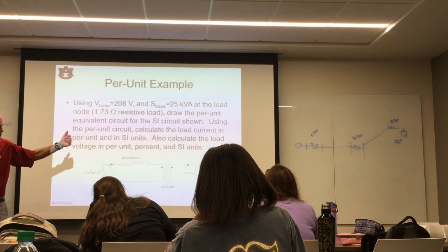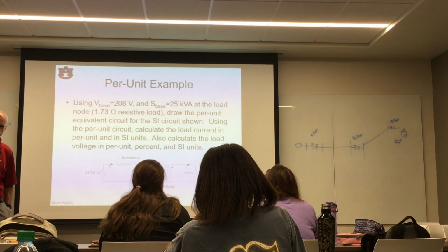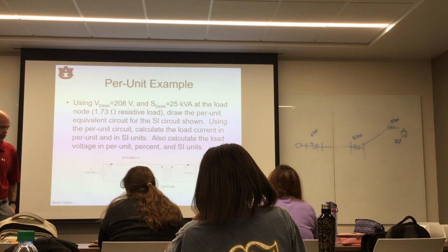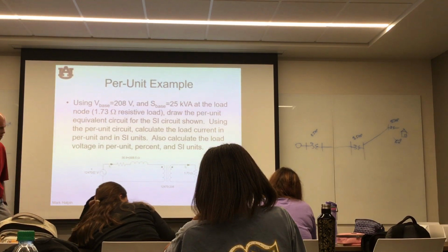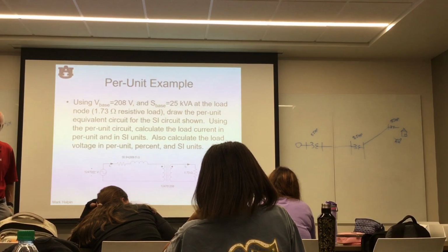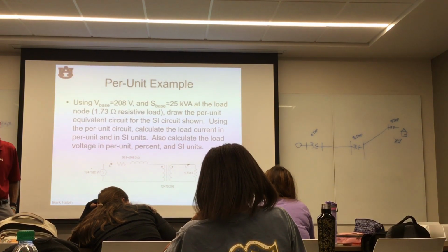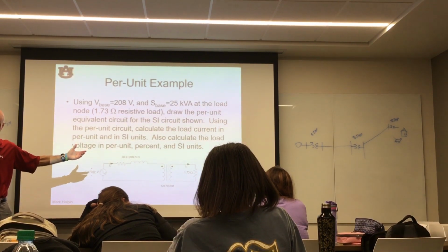As far as the transformer on the left, the one connected to the source, that we conventionally refer to as a generator step-up transformer, or GSU, the percent impedance is the percent of the ratings of that transformer.